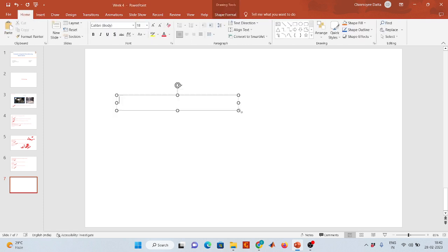So what is the significance of that ISO coding system? It's a standardization across the whole world. Everybody understands what SVJBL is, what SVJBR is, what a DNMG insert is. It's an ISO code accepted everywhere throughout the world.